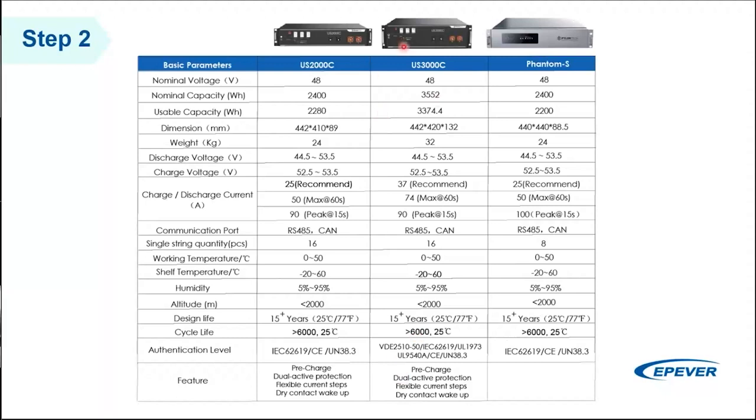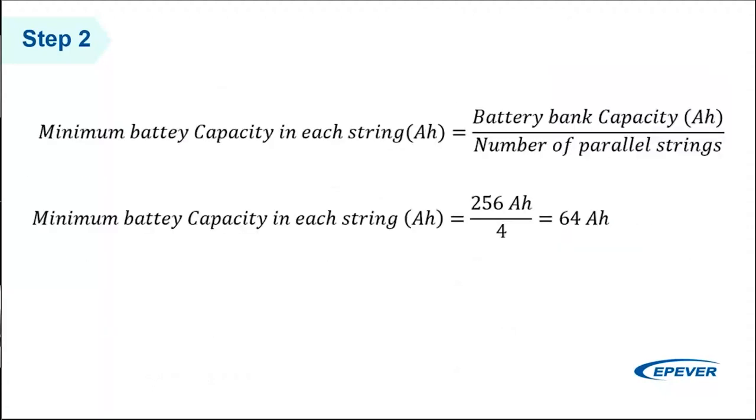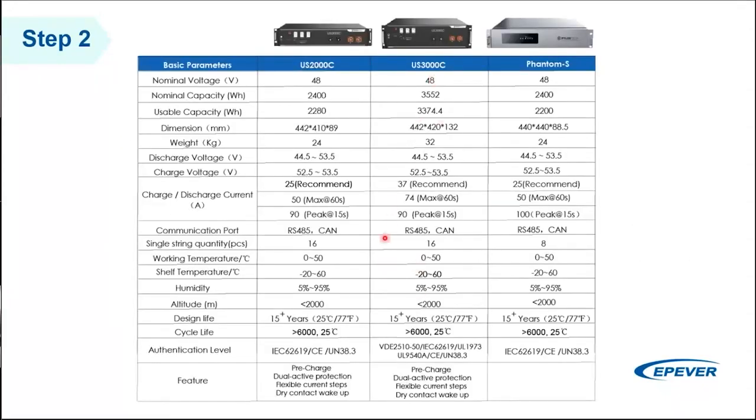Well, why these kind of batteries? Because of the simplicity and the modularity of these batteries, which, as you can see, the power is 3.5 kilowatt hours. So if I have 4 of them, I'm meeting the criteria that I mentioned here. I'm sure that this battery is capable of providing the power that I need. And this capacity makes it suitable for small and large accumulation systems.